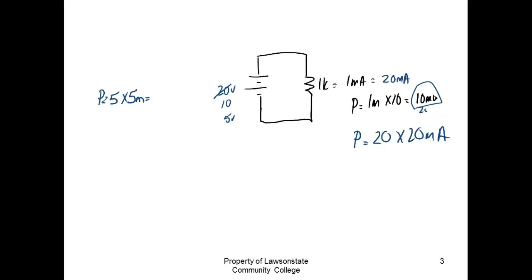But people get confused once we start talking about transformers. Transformers are not sending voltage. They're not sending current. They're sending power, but they're going to have to do it at a current level and a voltage level. So this is the difference between the source and what's going on at the load, right? You understand? Loads are designed around a certain voltage. So you couldn't take an air conditioner that's rated at 120 volts and say, well, I'm going to hook it up to 240, it'll get colder in here. As soon as you do it, the air conditioner is going to burn up in a heartbeat, right? Because that air conditioner is designed around 110, 120 volts.